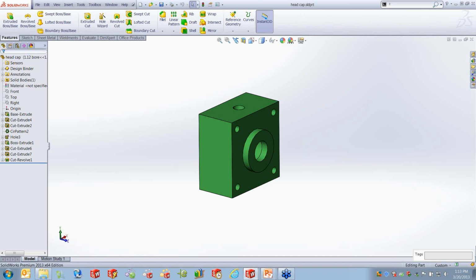Again, you can have a simplified configuration that doesn't have it. The next step up would be modeling them cosmetically and then actually modeling the threads fully. So, textured threads is a good alternative to actually modeling the threads. But if we're thinking large assemblies, that still may have an effect.